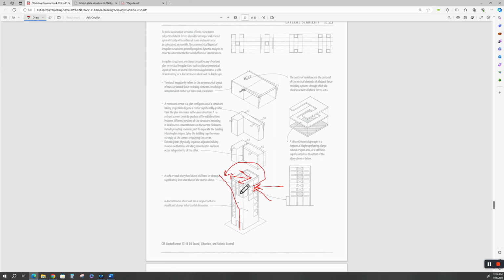So how do you reduce that twist? You reduce it with shear walls. Now, this particular is showing you discontinuous shear walls. All this would be like a concrete wall with holes punched in it, or cast in it, actually. Maybe it's tilt wall, or maybe it's diaphragms that they attach structurally and rigidly to the frame and produce shear resistance and torsional resistance, okay?